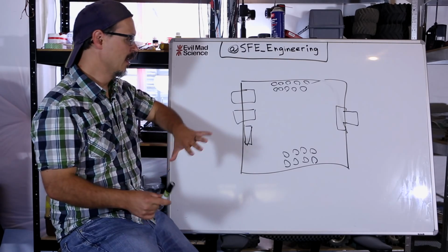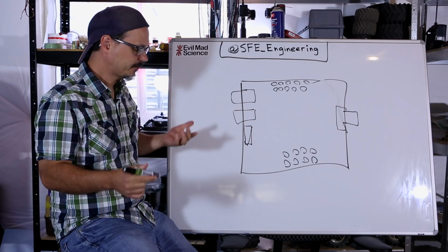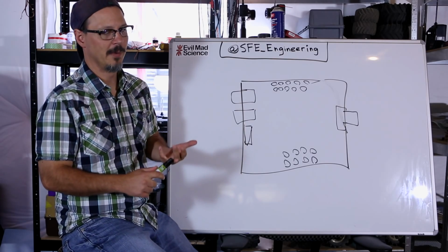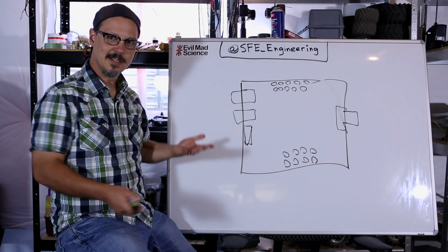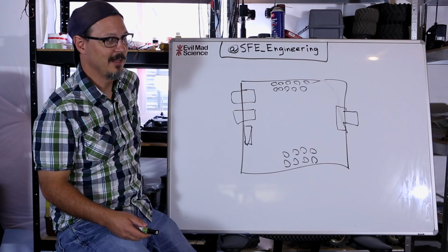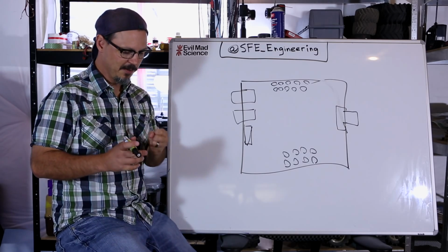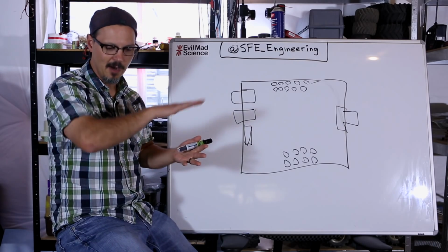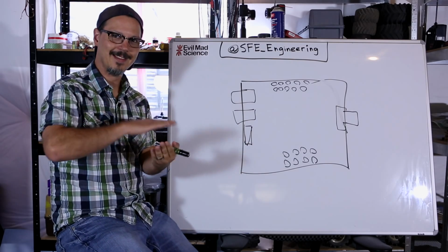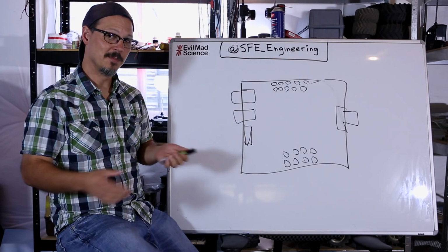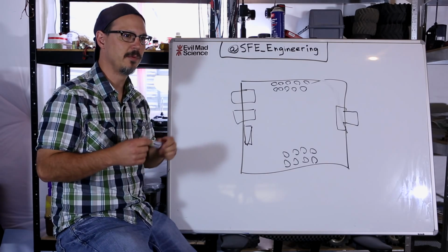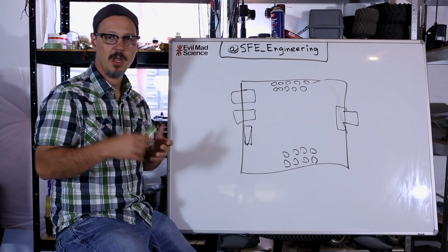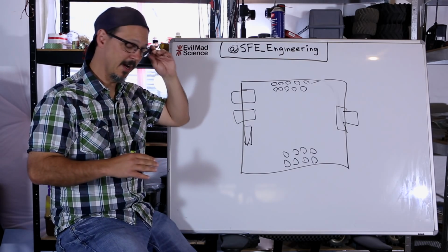Copper weight. When you get a PCB made, you can get what they call 1 ounce copper or 2 ounce copper on it, and maybe there's more, but I haven't seen them. And what that means, and I didn't know this until yesterday, is that if you were to take an ounce of copper and pound it until it's absolutely flat and covering 1 square foot, that's the thickness that this would be. What that comes out to be is about 1.37 mils, which is thousandths of an inch, so it's real small. 2 ounce copper would be twice that, okay?